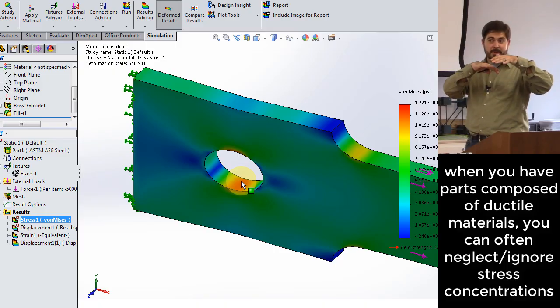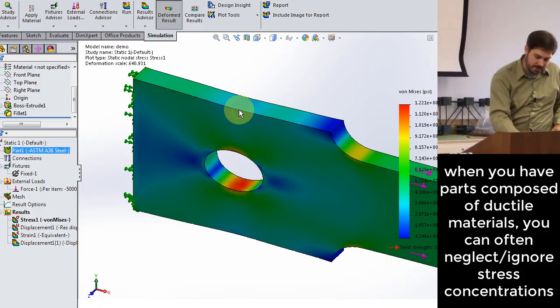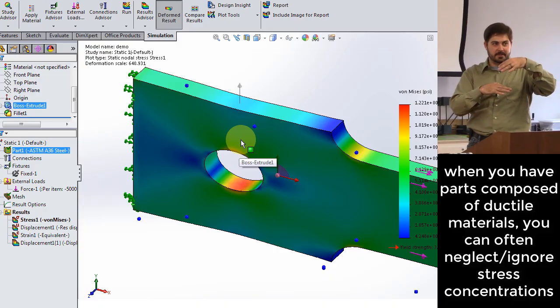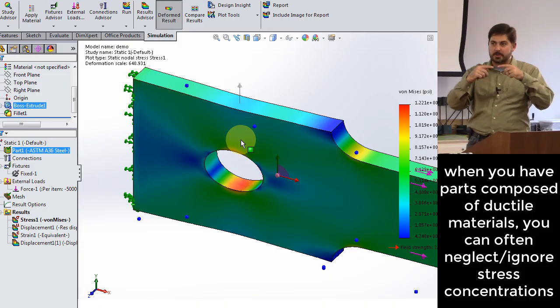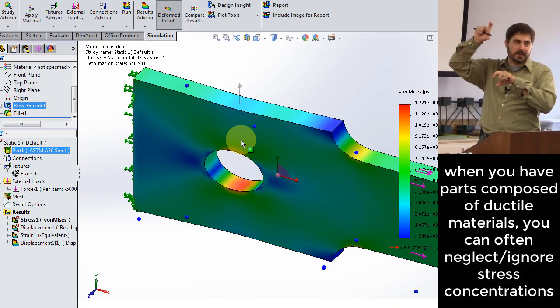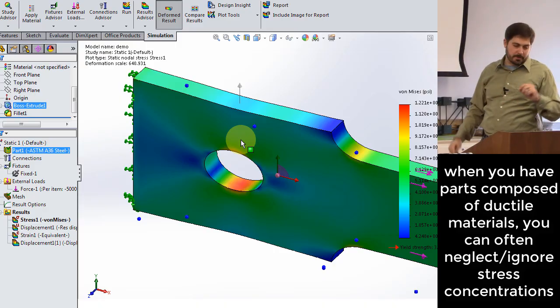Okay, so what it'll do, it'll move stress away from that zone and force the other material that's still here in this cross section, right? It'll force that material to carry more stress as it yields a little bit, and that transfers the stress outward into the material that's not currently holding a lot of stress, right? And so here's the principle we can draw from this.